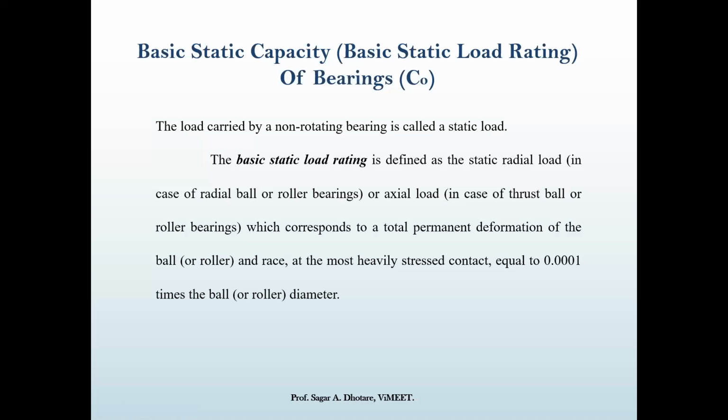When a static load is acting on a bearing, it produces some permanent deformation in the bearing, or you can say in the rolling element and races, which increases with increasing load. This deformation occurs due to the Hertz contact stresses. Normally, we define this deformation up to 0.0001 times the diameter of the roller, or you can say ball.